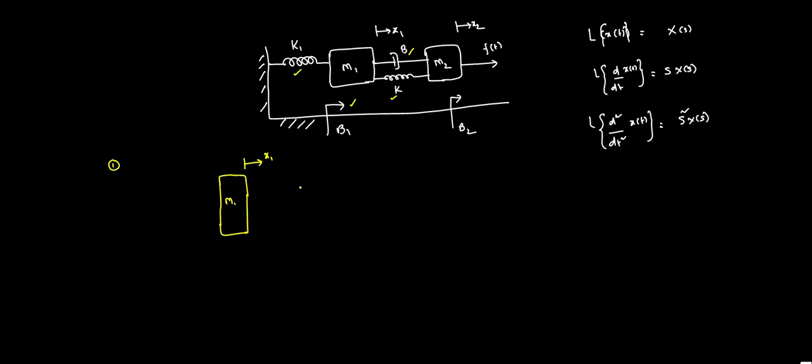So what I am writing is the force due to the spring Fk1, the force due to the mass, Fm1, the force due to the dashpot, Fb1, the force that is displaced in between, Fb, and the force that is there due to k, that is equal to 0. One important thing that you need to observe, this particular k and b exist in between m1 and m2, rest all are okay.